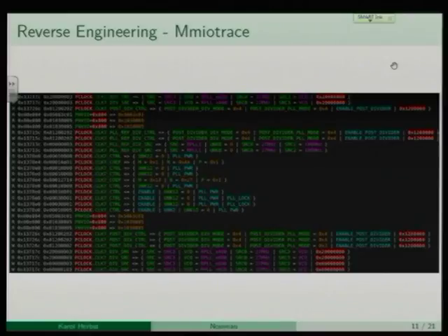If I understand correctly, this is not direct output of Mmiotrace, but some tool which translates the output of the trace in serial form. Yes, this doesn't show the output of the Mmiotrace. It's a tool to parse it. The Mmiotrace is basically just the white columns on the left side with the relative virtual address. What the parsing tool does is it reads the mapped region and subtracts the base address, so we have just the offset to the device, and the value passed is this colorful thing.